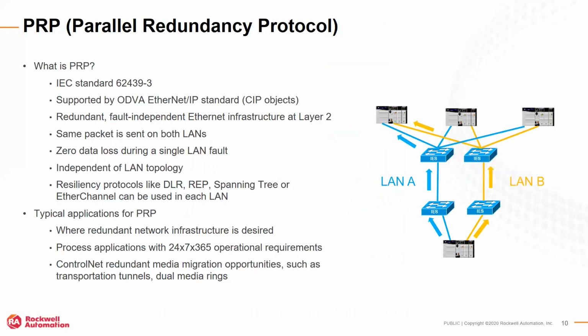Okay, Parallel Redundancy Protocol is a standard. It is not a Rockwell protocol per se, but it is an IEC standard. You can find Parallel Redundancy Protocol supported in many manufacturer switches. Usually the higher end ones you will find out. It is supported by ODVA. It's truly a redundant, fault-tolerant layer 2 design.